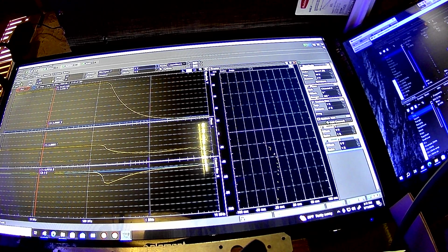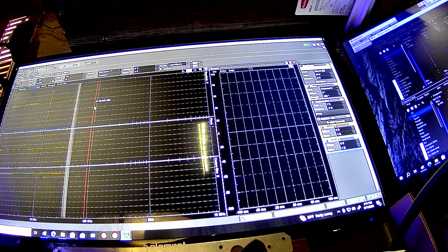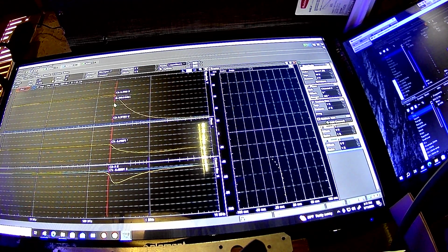As we see here, you start seeing it diminish right around 150, 140 kilohertz. Let's run it at a lower voltage. Now that's getting us out to 216 kilohertz. So for 12 volts peak to peak, you can get 216.